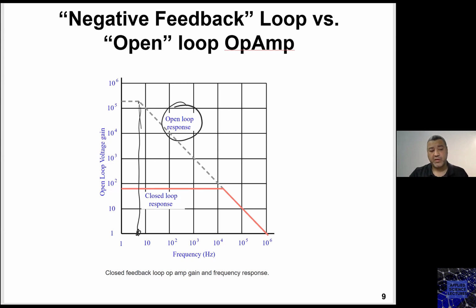Again, that depends on the application: what is the frequency of operation that you're interested in? I can increase this frequency of operation, having a flat response at a higher frequency. So if you compare this point, which is the maximum frequency of my signal at this gain, with this one, if this one is sub 10 hertz, this one is in the range of above 10 kilohertz, right?